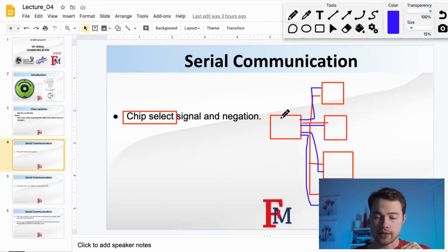So that wire is called chip select, which basically means that one of these wires is going to be set to active by this guy over here, right? For example, if this guy wants to talk to this guy, in that case this wire is going to be transmitting the active signal, and all other 3 wires will be transmitting a not active signal. And in this case, this guy over here is going to understand, okay, whatever is being transmitted, it's being transmitted to me, not to anyone else.